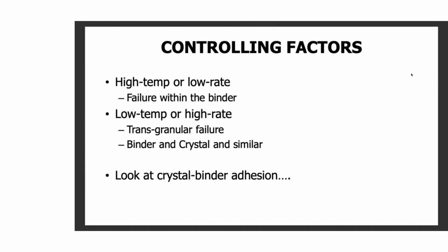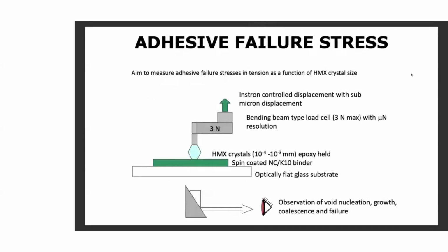So this causes us to do two things. Number one, look at the crystal binder adhesion. And number two, to look at the variation in response with temperature. So this was a setup that was developed by Dr. Andrew Williamson, and he had a layer of a binder which was spin coated on there, and this was a particular binder system of interest, and a fairly large crystal of high melting explosive HMX held in place by epoxy was glued on a probe, and that was then kind of bound to the plate.